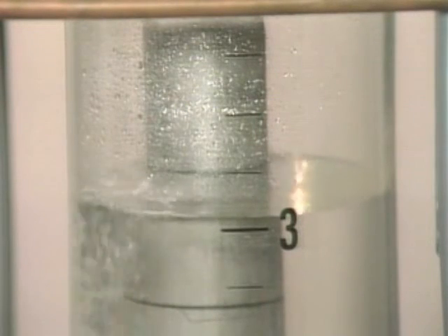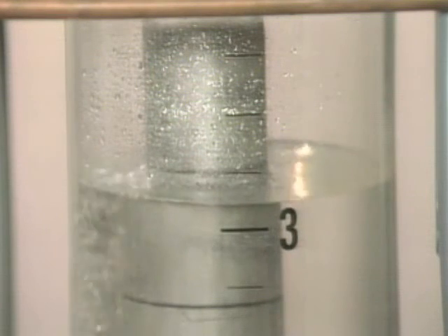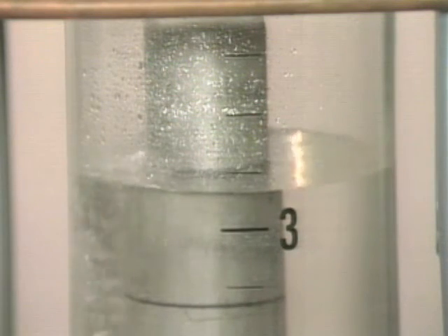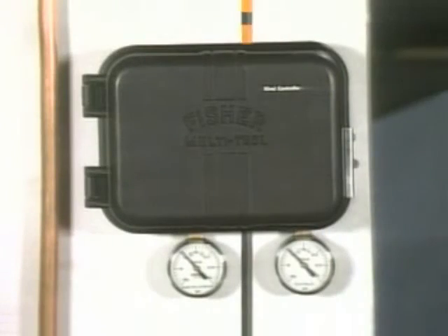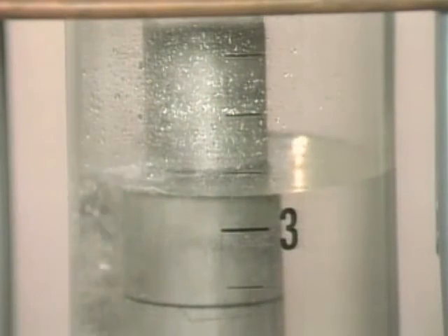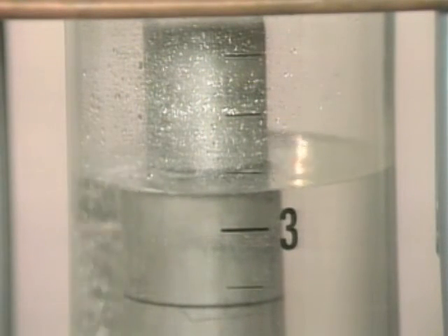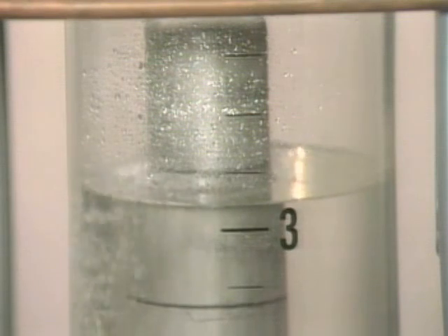In any case, when a process disturbance causes the input signal to a rate controller to change, the controller measures the speed or rate at which the input is changing and produces an instant boost to the proportional output signal. In effect, this action tries to stop changes in the input as soon as they're detected.